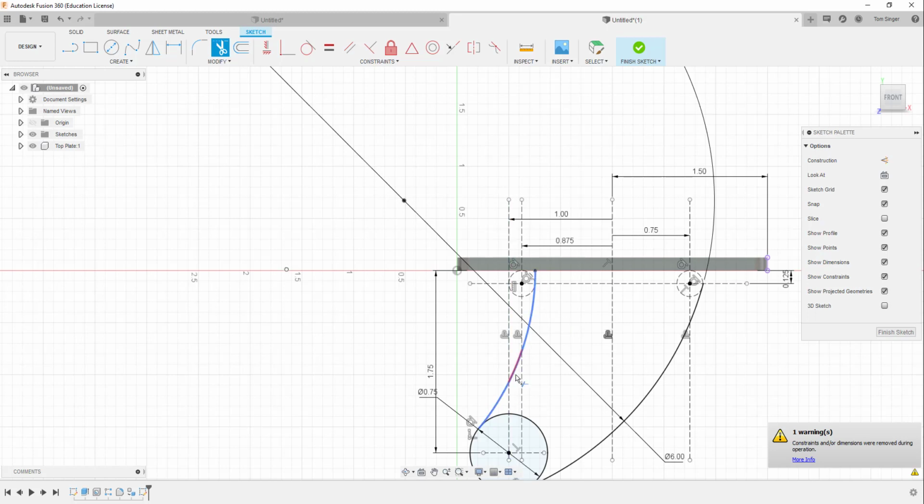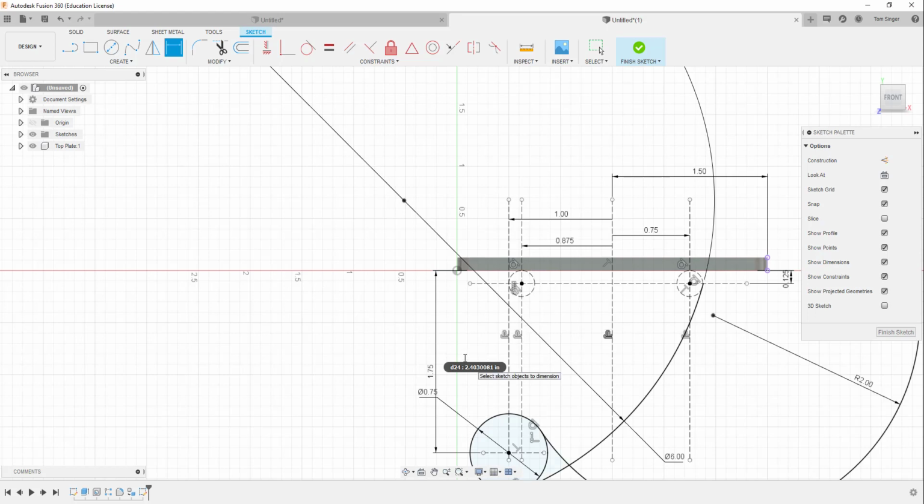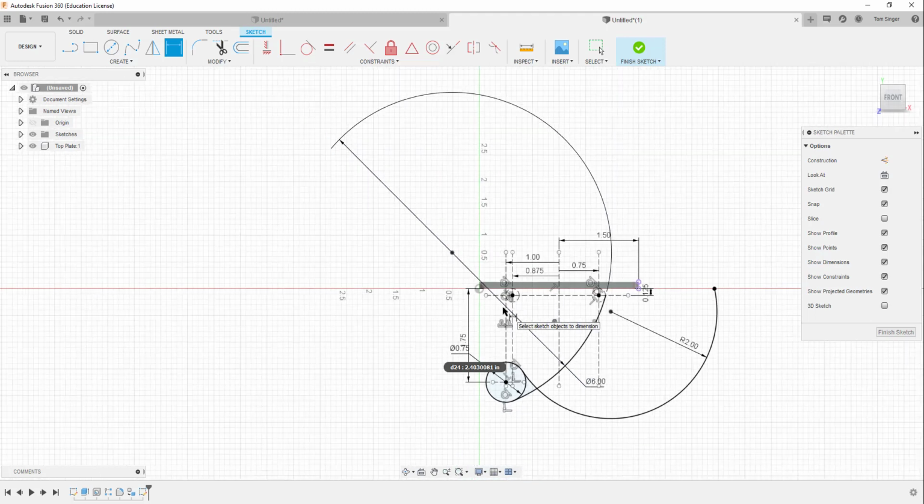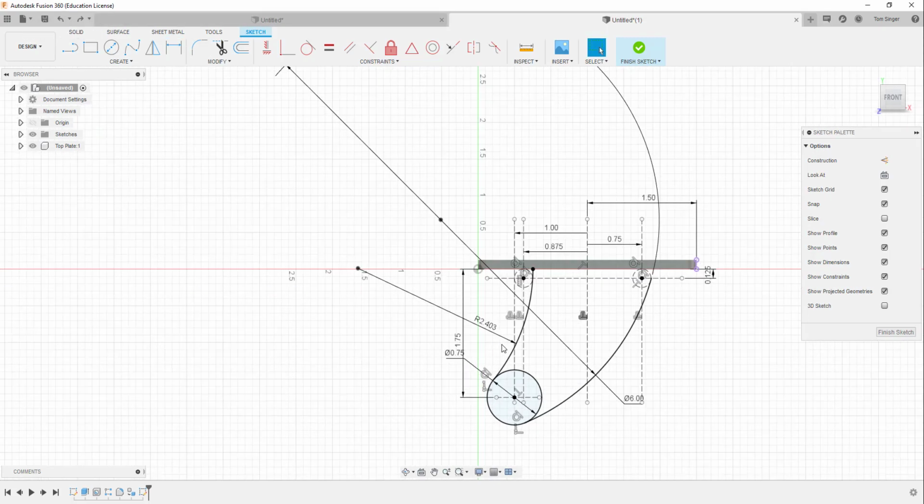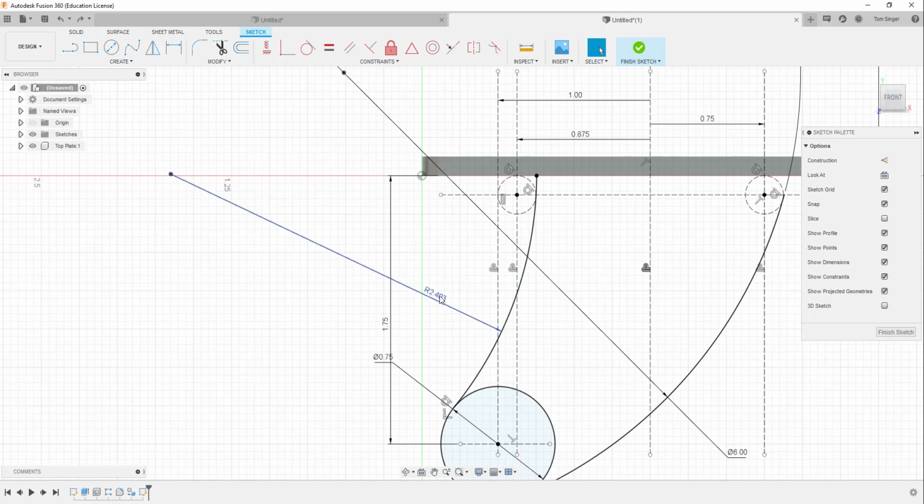Now, if I do this and I put in a dimension, it's going to be a radius dimension, and it's going to be 2 inches. And it doesn't like it. Did I put it on the wrong side? Nope, I got it on the right side. So it still doesn't like the 2 tangency positions. And so, of course, when you do the demo, it never works. So let's go ahead and trim this up even further. And 2.4 should be 2.0.